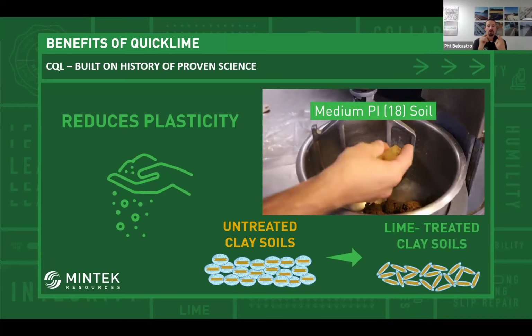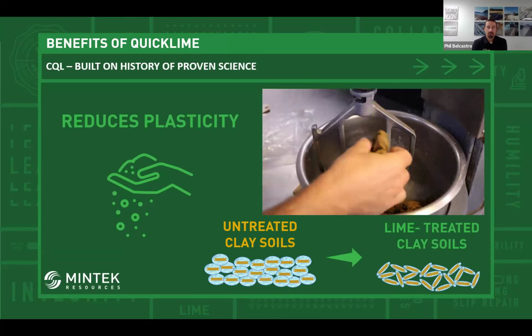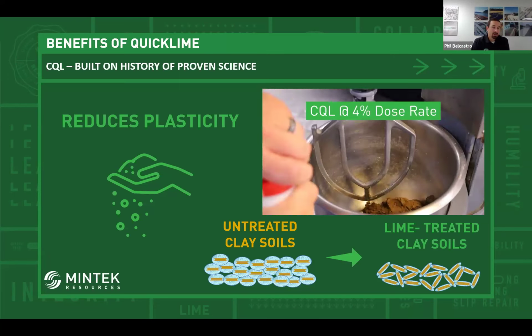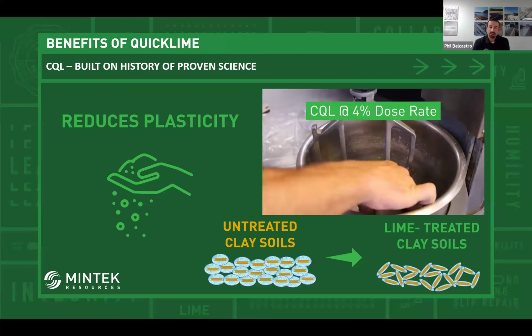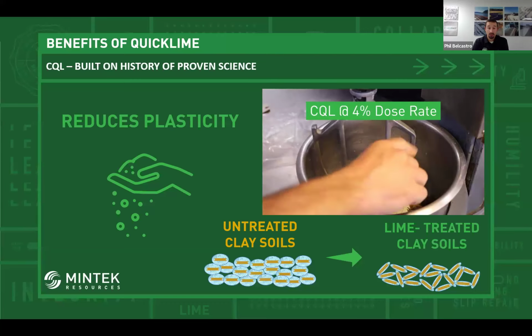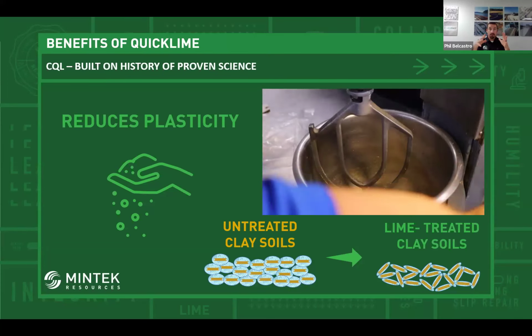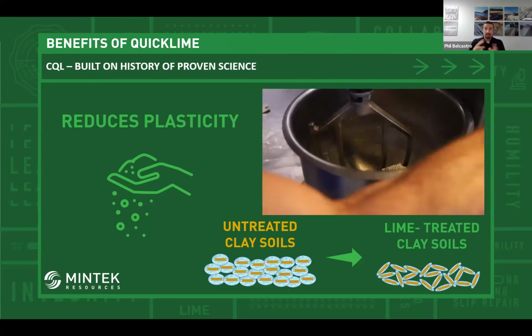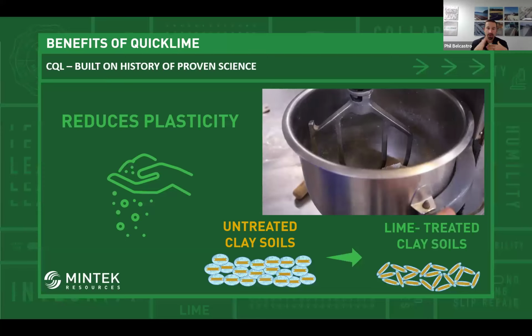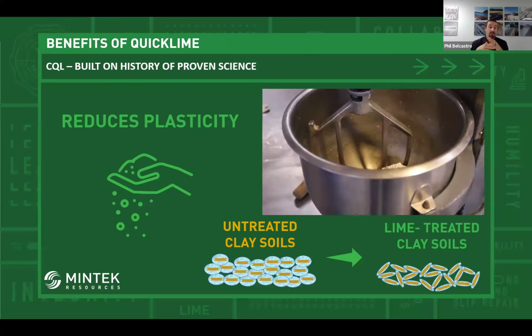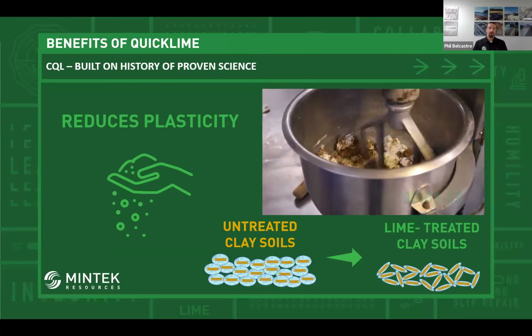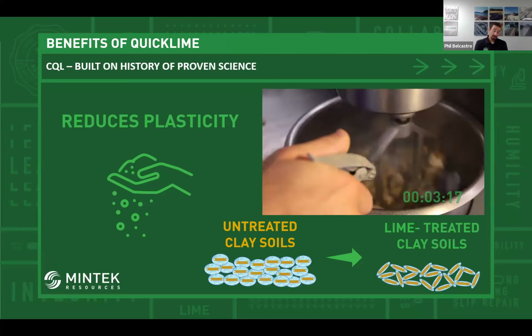Edge-to-edge orientation. Now we've had some cation exchange where our calcium has come in and pushed out other cations like sodium and potassium, which has resulted in molecular flocculation and agglomeration. So what the heck does that mean? Well, we've changed those charges. It's not all happening equally at the same time. So we're rearranging those particles to edge-to-face orientation, and that rearranging is helping to give us friction.